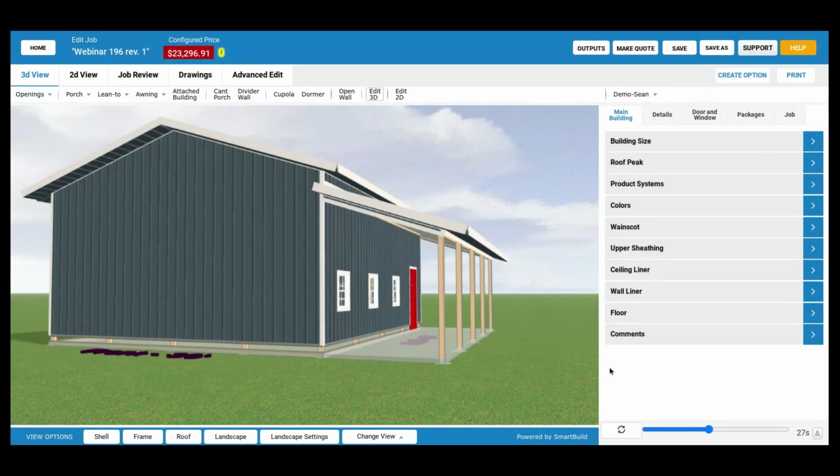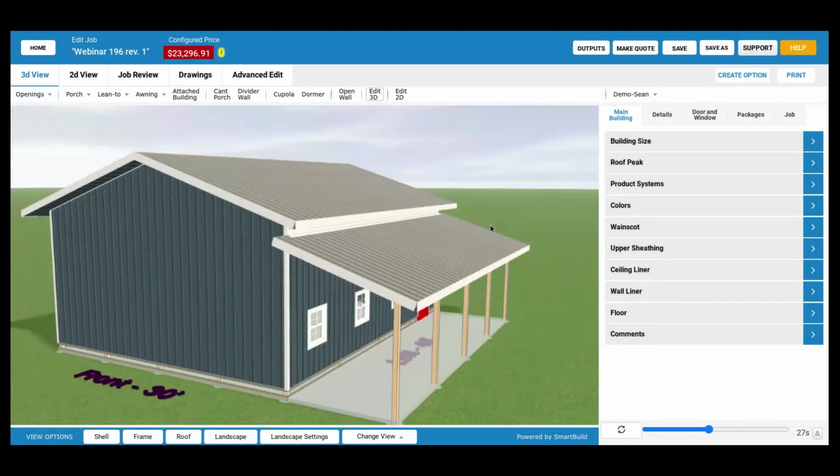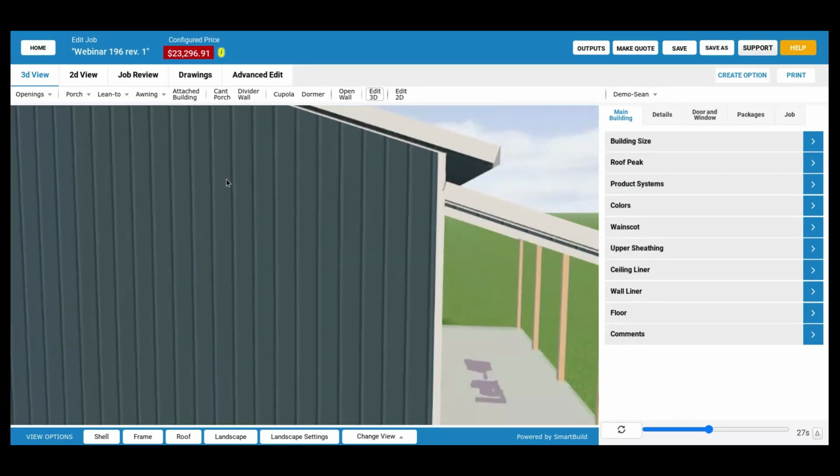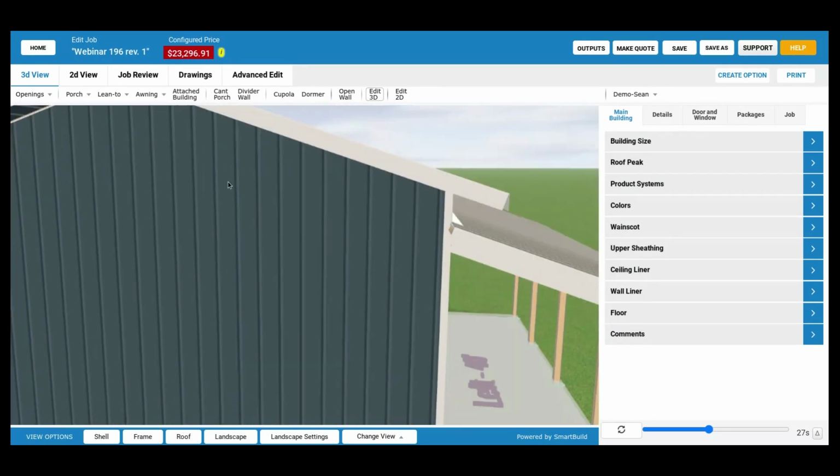Gable roof steel typically will be brought down from the peak to allow for ventilation, but monoslope roofs, we do not want the reduction, so all of the lean-to roofs need to have them added. Okay, so that is what he was talking about.